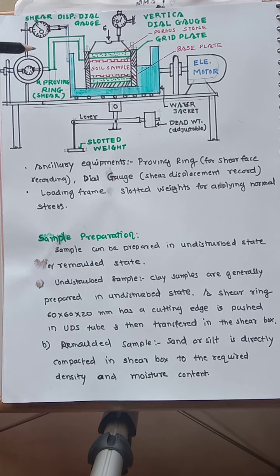It's a metal ring. Okay, inside, a dial gauge is already fixed and they are calibrated by the manufacturer. Okay, on this ring the load is applied in either direction by the manufacturer, and the displacement, which is very small within the elastic limit, is measured with the help of the dial gauge.